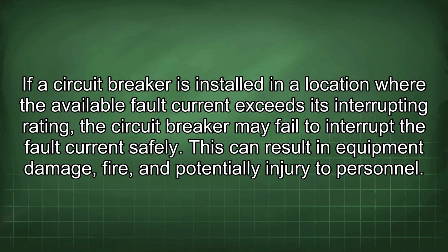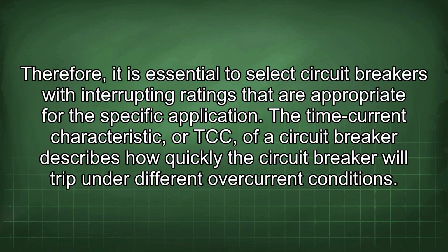If a circuit breaker is installed in a location where the available fault current exceeds its interrupting rating, the circuit breaker may fail to interrupt the fault current safely. This can result in equipment damage, fire, and potentially injury to personnel. Therefore, it is essential to select circuit breakers with interrupting ratings that are appropriate for the specific application.